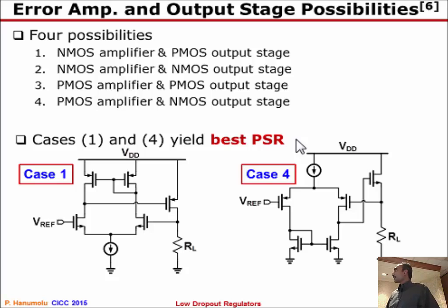In case 1, when you are using a pass transistor output stage, you want to have any noise on VDD appear on its gate so that the VGS is coupled, or VGS is 0 ideally. Right? So for that reason, I would like to use type A error amplifier that I have shown here. And conversely, if you are using an NMOS output stage, then you would use type B error amplifier.